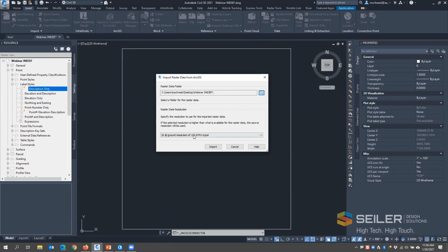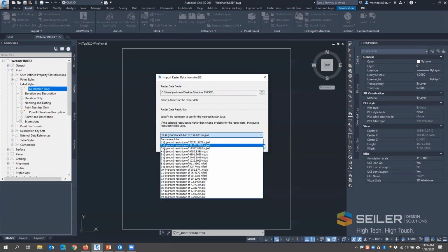And here you could choose your ground resolution. If you're familiar with bringing in imagery for InfraWorks from the Bing imagery, you have these same stepped resolutions. So you have an indexed resolution that equates to whatever the distance per pixel is. At the lowest, it would be a flash of a blob of color, down to 1 foot, 0.229, almost a little less than 1 foot per pixel, or 0.29 meters per pixel. I'm going to choose something here in the interim just so it loads fast. I'm going to choose this ground resolution of 2 meters per pixel.